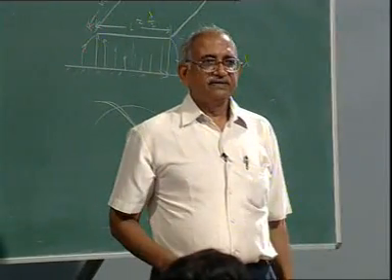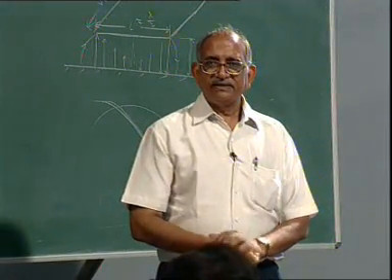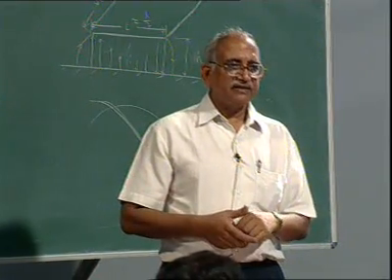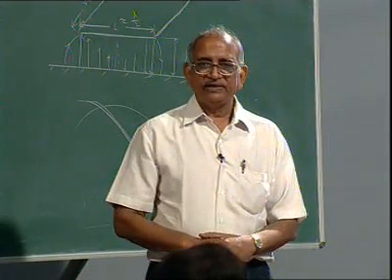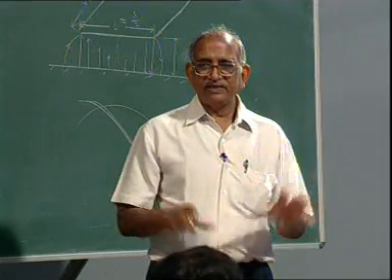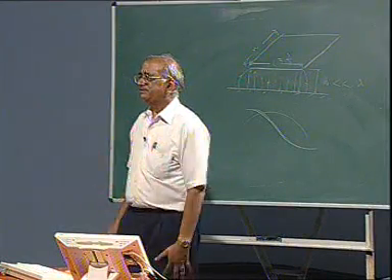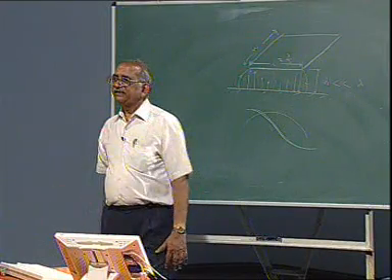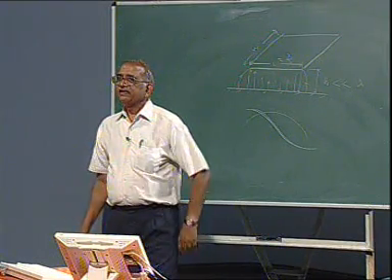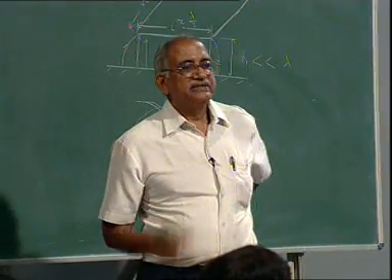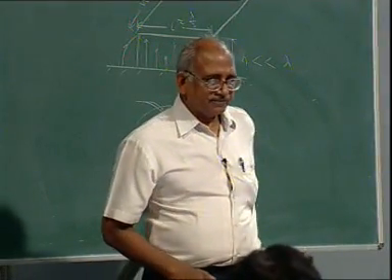That is why for these planar antennas, their characteristics are determined by the dimensions in the two directions, in a plane only, and the third dimension, that is along the thickness, does not count over here. All the characteristics are independent of it, the reason being that the thickness of the substrate is much less than wavelength. Okay.